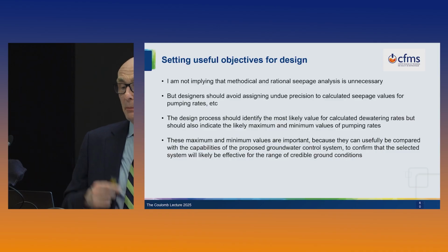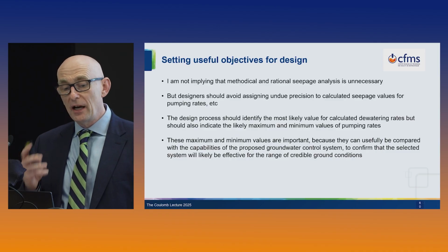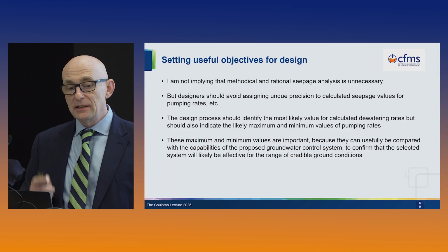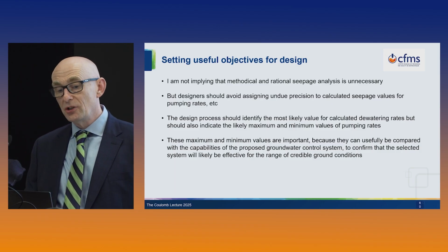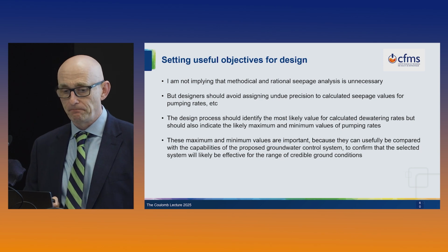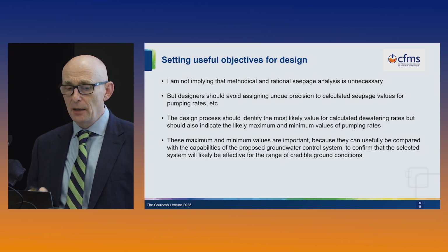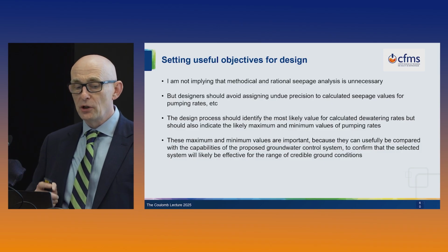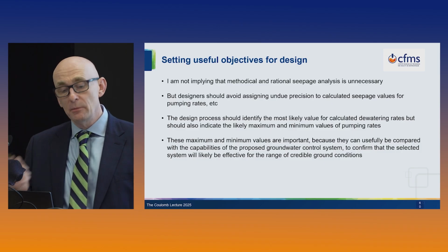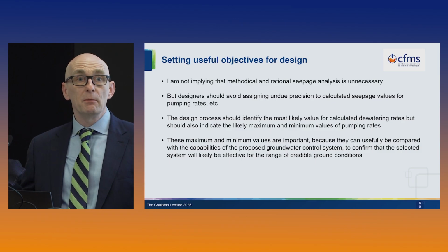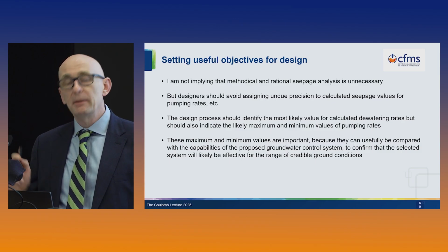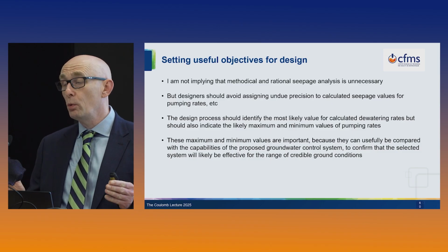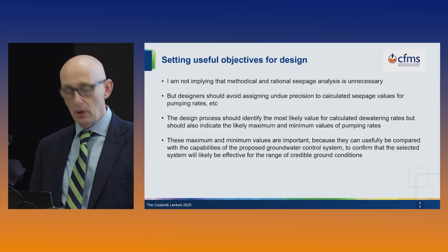I don't want you to think that I'm implying that it's unnecessary to try and carry out a methodical and rational seepage analysis. My message is designers should avoid assigning undue precision to their calculated values of pumping rates and so on. My recommendation is the design process should identify the most likely value for calculated dewatering rates, but should also indicate the likely maximum and minimum values of pumping rates. These maximum and minimum values are important because they can usefully be compared with the capabilities of the different systems to confirm that the selected system will be able to cope with the entire probable range of values.